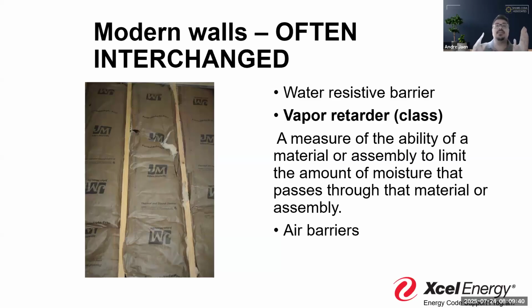So this is going to be the ability for moisture to penetrate through other materials, and coalesce. So this is when we're saying, okay, we know we're going to create moisture on the inside of the building. We also are sealing this thing really well, right? That's our air changes per hour. We're also doing our best to seal in this exterior component. So now we've got to tell this water where to go because we don't want it just collecting in the wall cavity environment, right? We don't want it just hanging out there to create mold, mildew, rot, any of those problems.